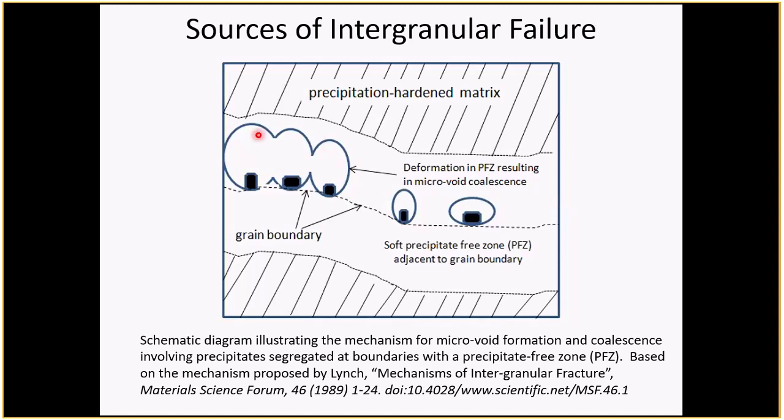And there is this mechanism of creep that can occur at very high temperatures. We've talked about diffusional creep in some of the earlier lectures, especially to do with rate theory and mass transport, diffusional mass transport. But now we're talking about the thermal mechanism where vacancies are the primary driving force for any diffusional creep.